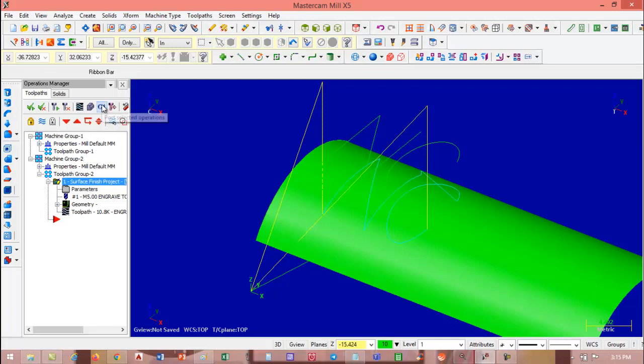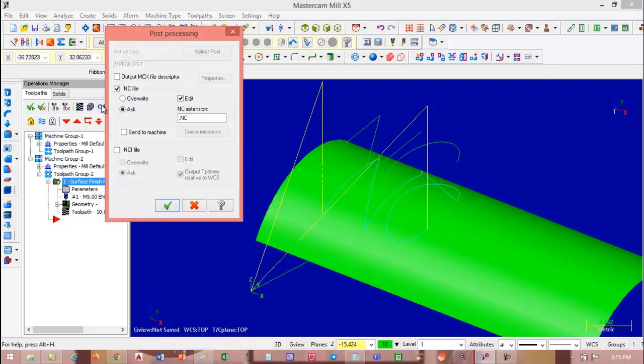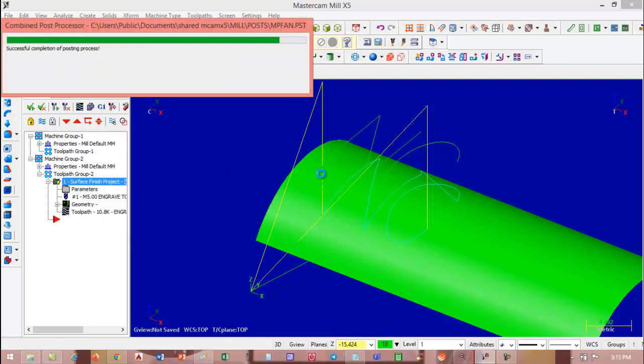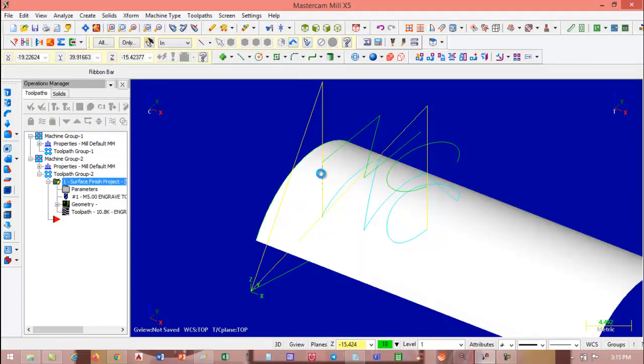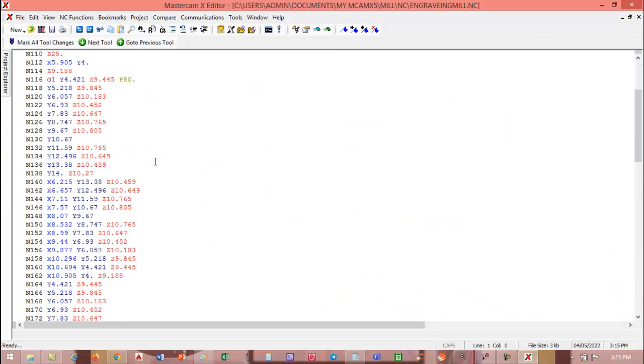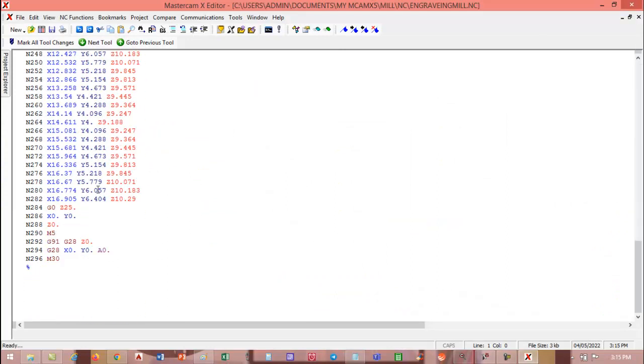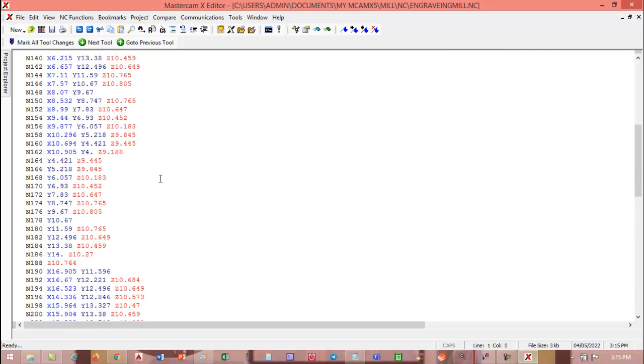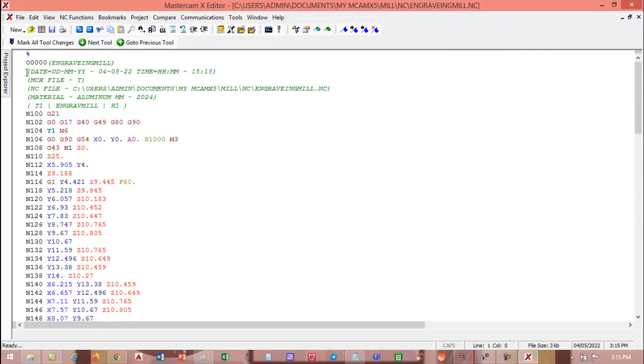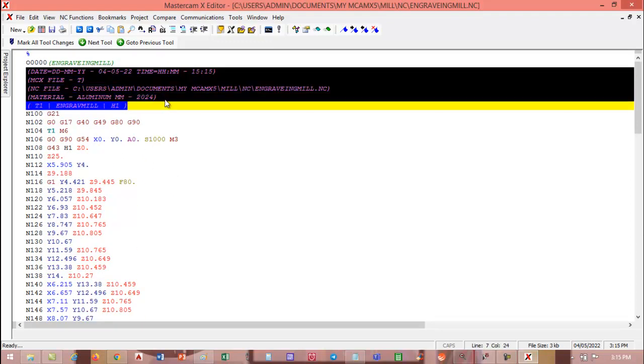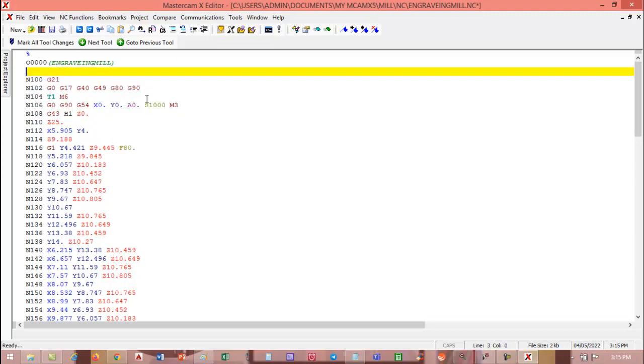So now I want to check the G code M code program, which we can transfer to CNC machine through DNC. So here for FANUC control, NC file, overwrite and edit, and then say OK. Now this particular program, we can send to VMC machine after that. So this is the complete procedure, and this program which has been generated for FANUC control, you can transfer to CNC machine. This top 4 lines, if required, we can keep it, or else you can delete this.